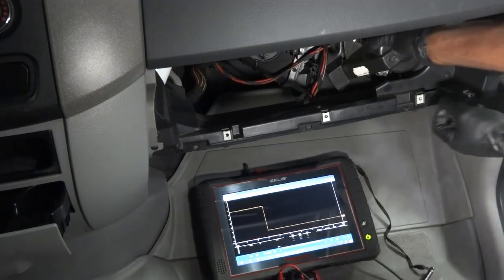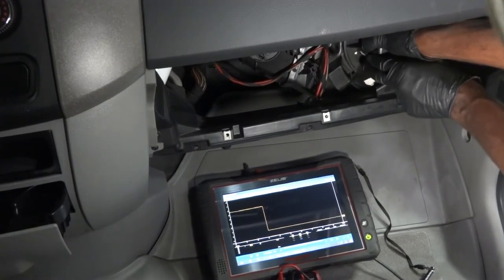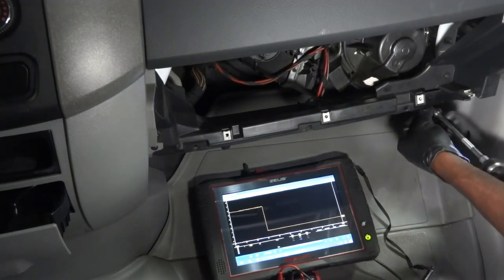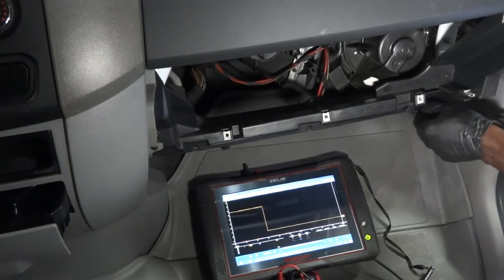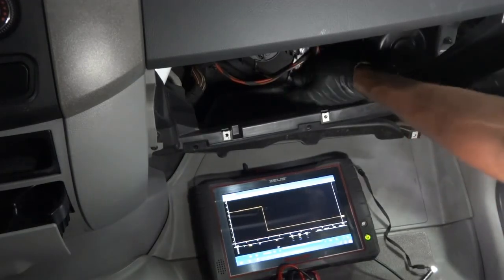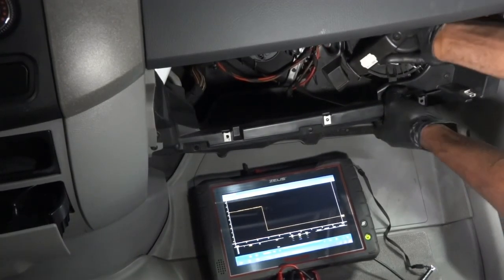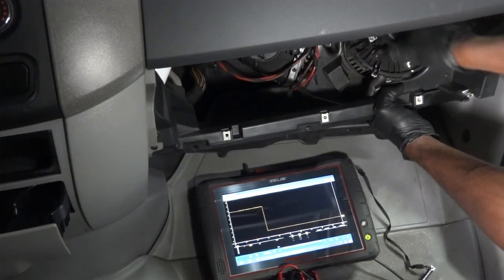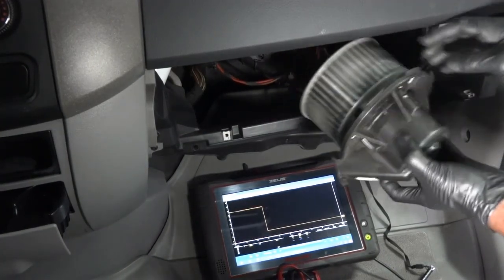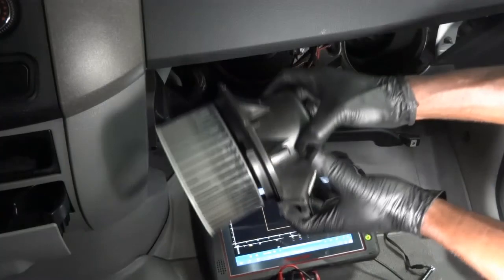And this blower motor, the way you remove this, you just twist it counterclockwise like this. Actually, let me undo this bolt here first. There's a vent tube underneath here. Okay, so you just twist it, and then here it comes. Everything is plastic here, so just work it out slowly right here, and then pull it out, and here it comes. So here is the old blower motor. I'm gonna set it over here.